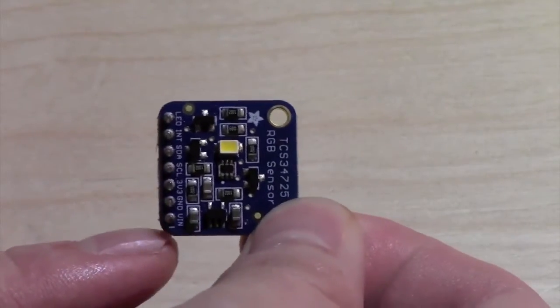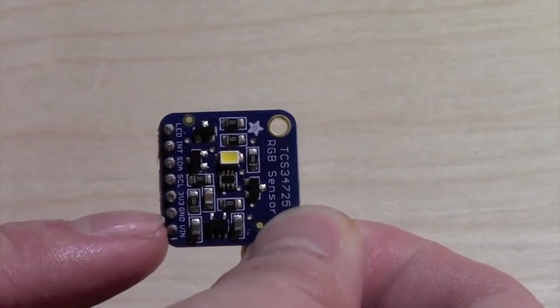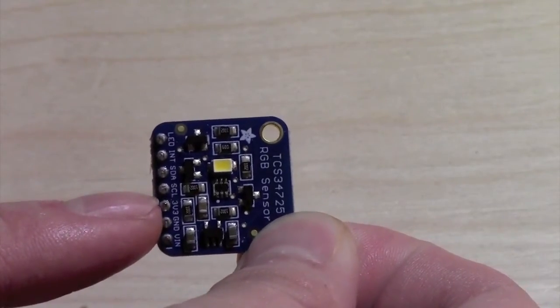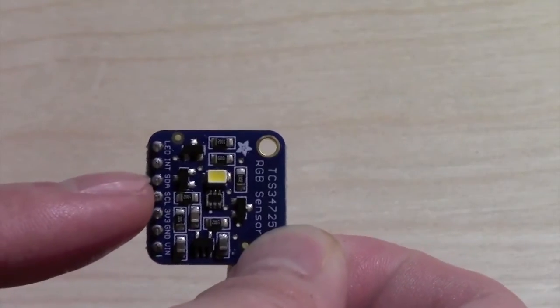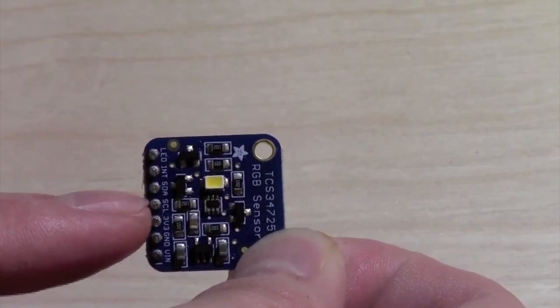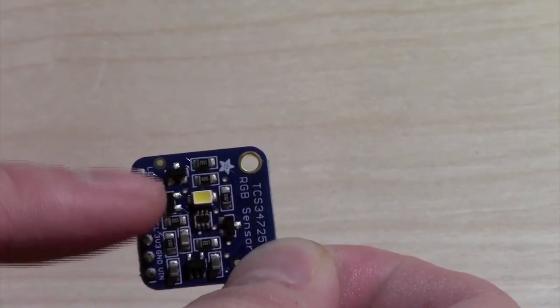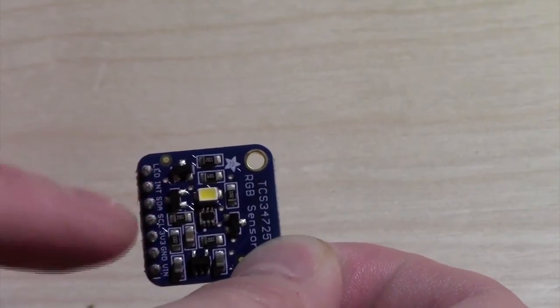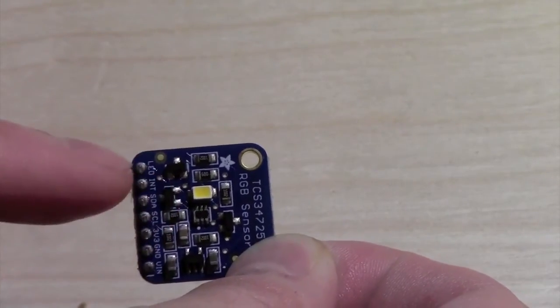We're not going to use this one. This pin is used if you want to power this on 5 volts. What we're instead going to do is power with the 3.3 volt line and the ground pin. Then, as you can see, there's the serial data line and the serial clock line that we need for I2C. And this is the LED pin if you want to turn the LED off. By default, the LED gets turned on when you power it on 3.3 volts. If you connect this to ground, it will turn off the LED if you need to.